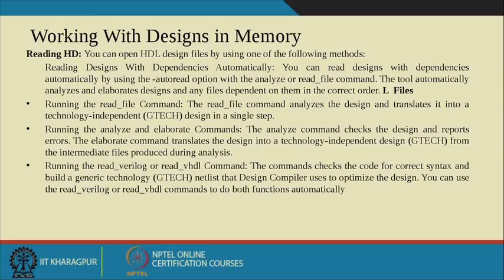Now, working with the design in memory. As I said, whenever we read something, whether in Verilog format or DB format, it is saved into Synopsys memory. So how do you read the HDL? You can use the read_file command for reading the Verilog or VHDL file, and then it will be converted into the generic library provided by Synopsys.